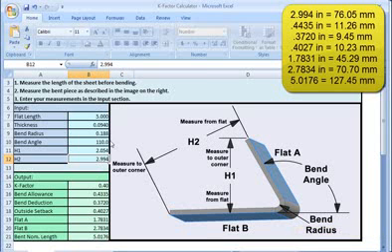The bend angle is also a critical measurement. Try changing it to 109 degrees. If you get a K-factor greater than 0.5, you can rest assured that your measurements are off. The K-factor is essentially the percentage of material that is compressed. In this case, 53% of the material is compressed, which causes the nominal length of the material to decrease. The K-factor was 0.4, so just 1 degree caused over a 25% change. Set the bend angle back to 110 degrees.